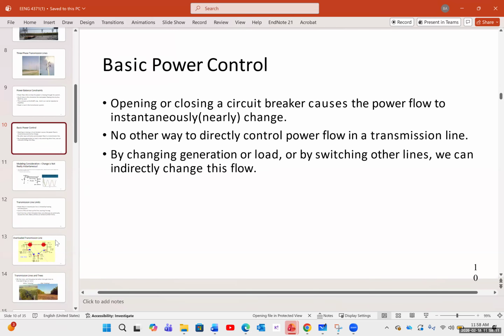The thing is, most of the time we cut back the power, but it's not just the generator and load. I'm glad that you asked that. We cannot just increase both, like the generation and load as well. We have a limitation on the transmission line as well, and that limitation is determined by the resistance that we have in a transmission line. And the loss in that resistance is I squared R.